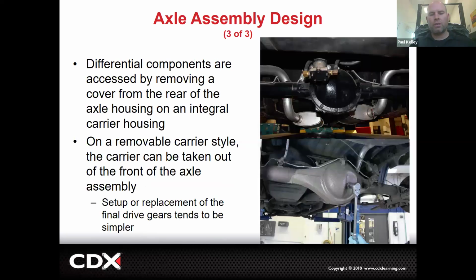And an interesting point, I think generally you'll be able to see it right here. If you look, this ring gear is kind of big. These bearings get oiled pretty quick, but this front differential, this front pinion bearing sits up kind of high, because you see how this drive shaft is sloping upward, right? That front bearing, that's up the highest. So if your differential runs low on fluid, that's typically the first bearing to start complaining about it.